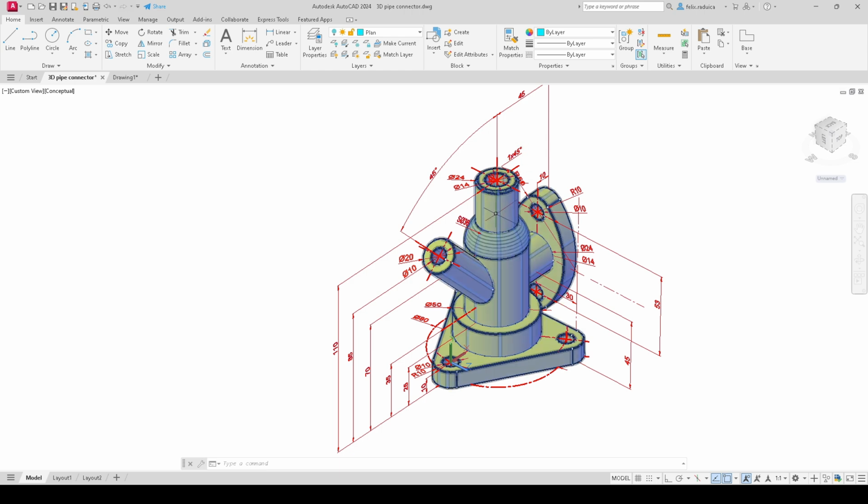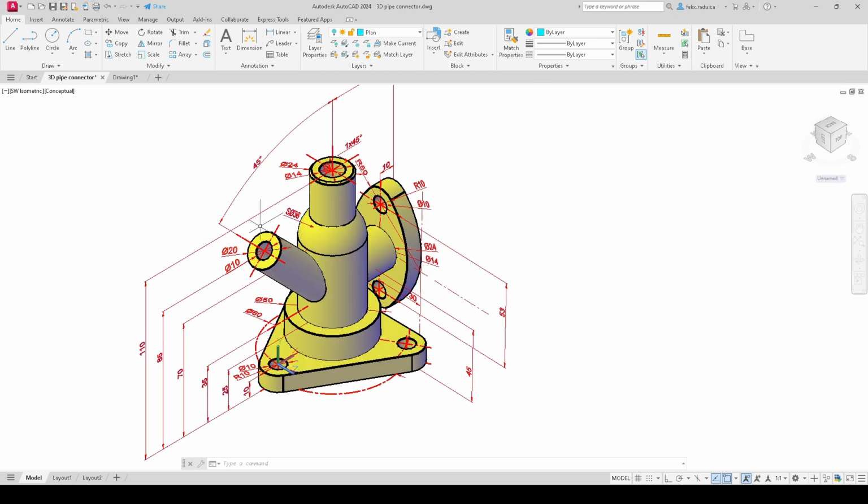So we have to keep the geometry and place it on the proper layers and do a final subtract at the end, because they have to be joined together. The outside geometry needs to be union together and the inside geometry needs to be union together, and then from the outside geometry we'll subtract the inside geometry once we have all of the geometry in place. We'll move on to creating the tilted cylinders here.